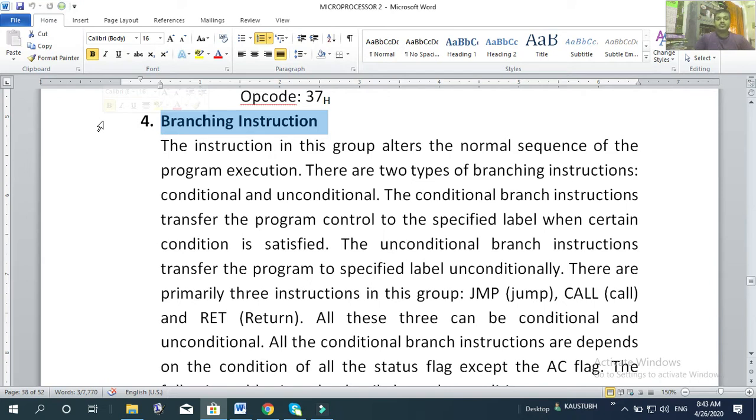That means from instruction 2, without executing instruction 3, it simply goes to instruction 6 of the program. So that means it alters the normal flow of program execution. And I hope you understood how it alters. How it alters, because the program counter always holds the address of the next instruction in a normal sequence. But if I would like to alter it, that means what? Forcefully I have to enter the address to which it needs to alter into the program counter.